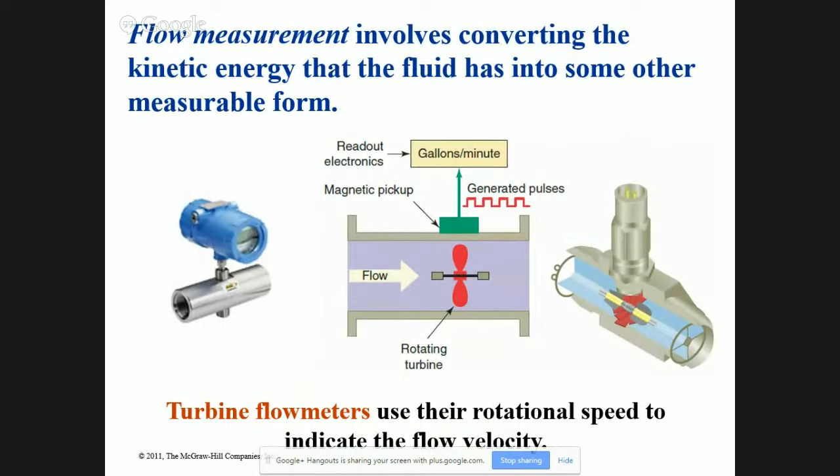Most everybody uses them, they're a little bit more pricey, but like a Venturi effect. Remember the Venturi effect from fluid power? When you gently restrict fluid flow, we get a pressure drop in the middle. Well, they sell Venturi meters because if that was acid right there, that paddle wheel would go away before long, it would dissolve. With a Venturi effect, we tell it what the specific gravity of the water is and the diameter of the pipe.